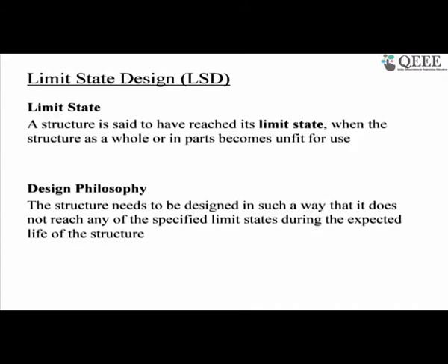Now, the limit state design philosophy is that the structure needs to be designed in such a way that it does not reach any of the specified limit states. Just now I mentioned that there could be different kinds of limit state. Depending on what limit state you specify, the structure should be designed in such a way that it does not reach those limit states during the expected life of the structure.